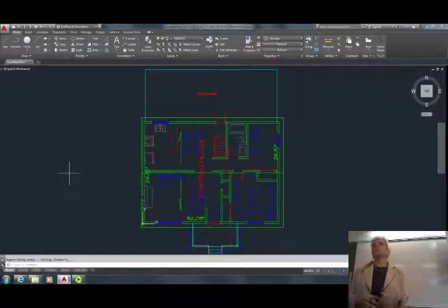Feel free to do more work than I'm asking you to do. If you want to have your entire project printed in standard architectural scales in 1/4 inch, you could lay out few sheets, and if you follow the instructions that I'll give you today, all of your 1/16 texts will be blown up by 50%, and they will become the drafting standard 1/8 of an inch.